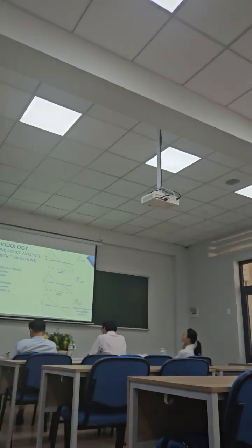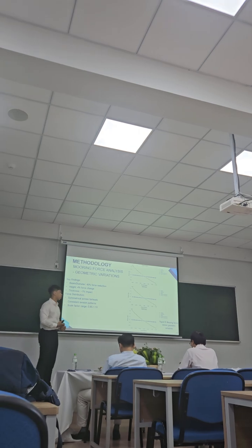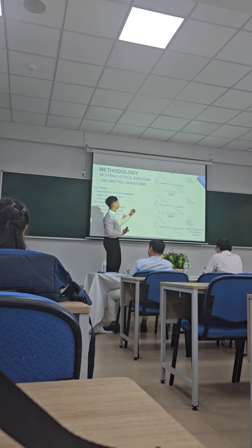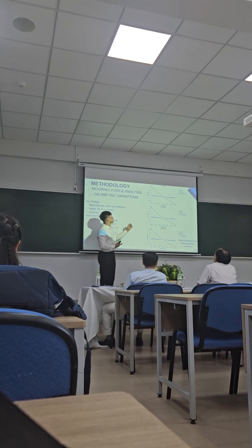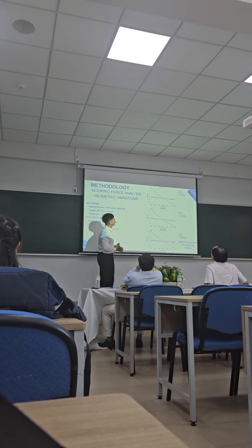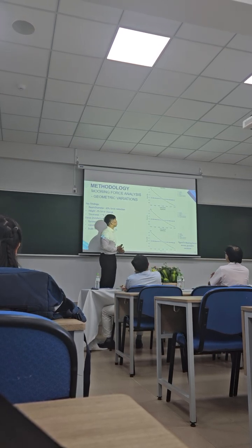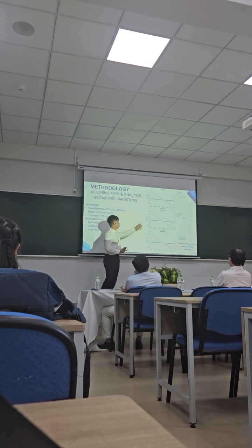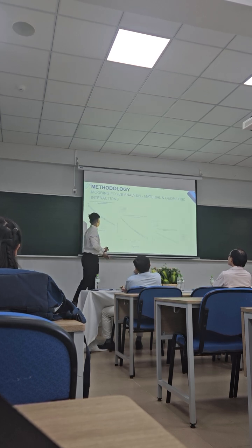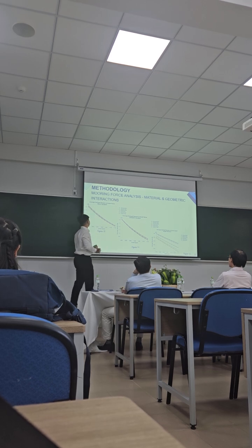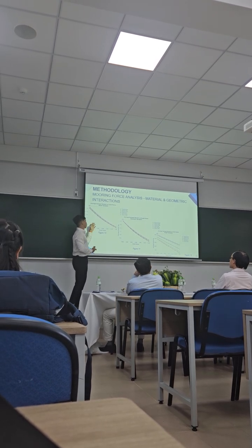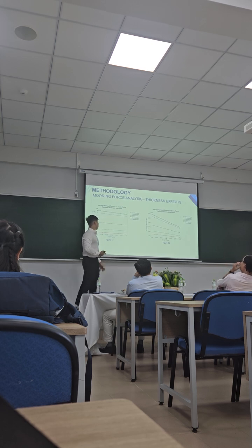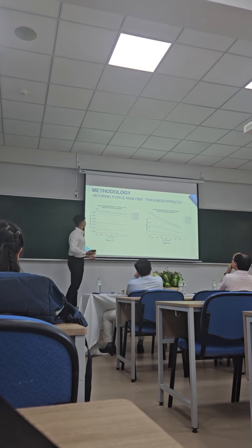And as you can see in figure 9, this is the change of the mooring forces across the geometric variations. You can see that the beam length and the column diameter have a significant influence, while the column height and the thickness have an effect but minor. The mooring forces are symmetrical across different columns. From figure 10 to figure 12, we can see that the trend of mooring forces is consistent across different materials. Similar with figure 13 to figure 14.